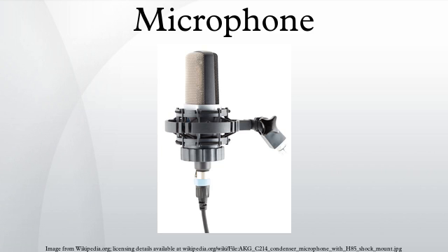60268-4 specifies that frequency response should be measured in plane progressive wave conditions, but this is seldom practical. Close-talking microphones may be measured with different sound sources and distances, but there is no standard and therefore no way to compare data from different models unless the measurement technique is described.